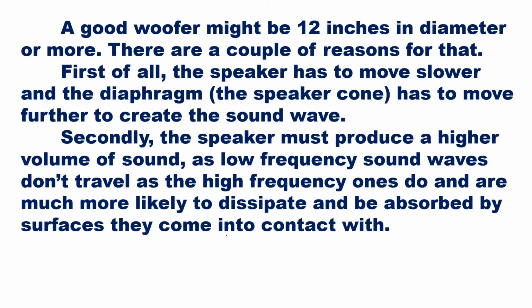There are a couple of reasons for that. First of all, the speaker has to move slower and the diaphragm, that is the speaker cone, has to move further to create the sound wave. Secondly, the speaker must produce a higher volume of sound as low frequency sound waves don't travel as the high frequency ones do and are much more likely to dissipate and be absorbed by the surfaces they come into contact with.